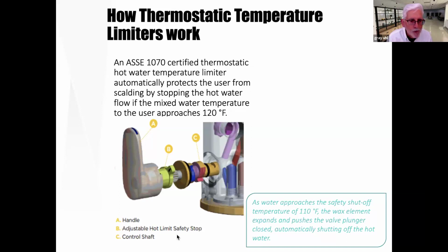And the other thing I will share with you, in a public space, the building maintenance guy, in many of these faucets, this one in particular, if you want to not let the user adjust the temperature, the maintenance guy can use this little lever, set it to where they want, and then they take the handle off. They remove the handle, and a little decorative plug covers over that whole assembly. So there's multiple ways to scald this cat.